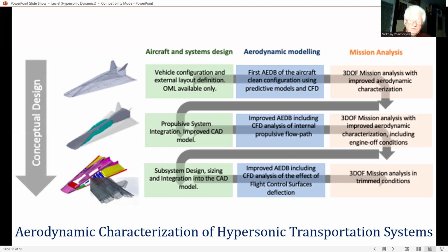Indeed, all of the local surface inclination methods in this part of our lecture are embodied in an industry standard computer program called the Hypersonic Arbitrary Body Program, originally prepared by Gentry, and for this reason frequently referred to as the Gentry program. This program has been in wide use throughout industry and government since the early 1970s.